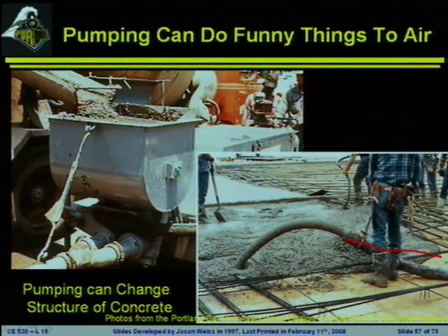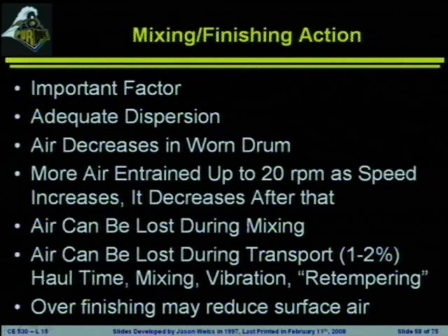The pumping action itself can change the structure of concrete because you are compressing the material and putting it under quite a bit of pressure. So occasionally you'll see it breaking down the aggregate, and you'll see it breaking down the air inside of the system. The mixing action is again going to be an important component.